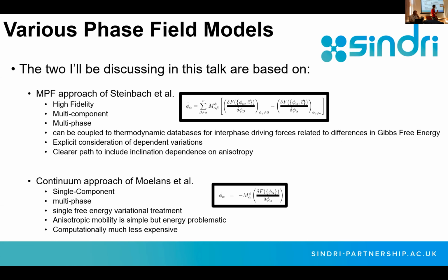So the two phase field models I'm going to talk about are one based on the multi-phase field approach of Steinbach, and the other based on the continuum field approach of Moelans. The approach of Steinbach is, I'd say, higher fidelity. That's the important thing. It's multi-component as well. So a multi-component, multi-phase field method. And I'll show you the equations. That's actually fully implemented. The multi-component, multi-phase part is fully implemented.